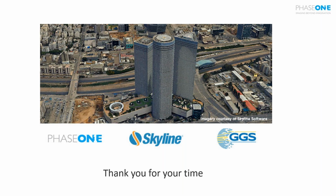So the difference between them is, Tel Aviv was a massive project, and trying to do that entire project in 3 centimeters would have been twice as many images or more. So there are financial aspects to every decision on what resolution to fly. Obviously, everybody would love to collect everything in 1 centimeter, but then you have to process 1 million images and fly for a week instead of a day or 2. So there are a lot of inputs and criteria for how to decide.